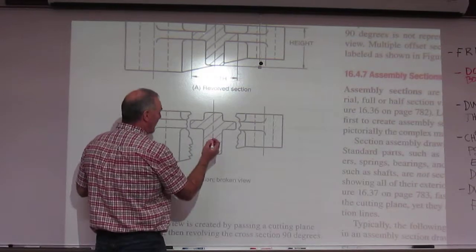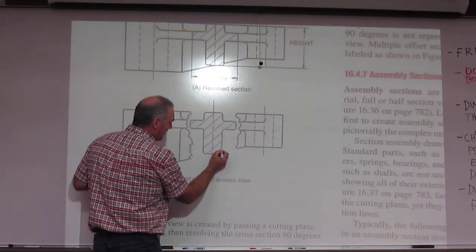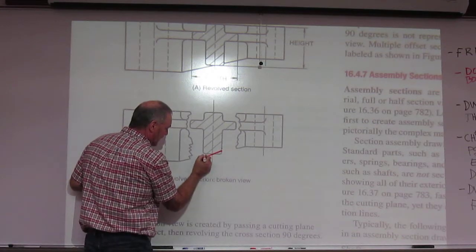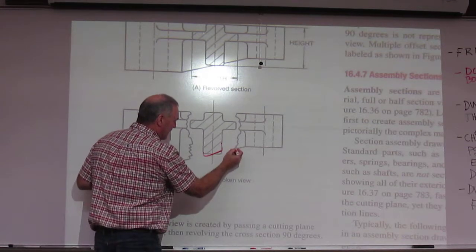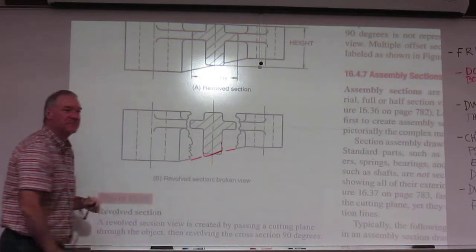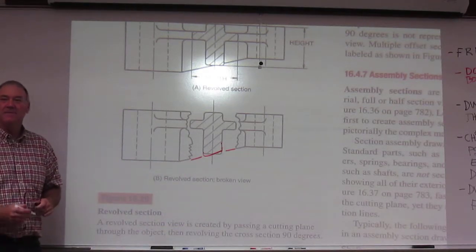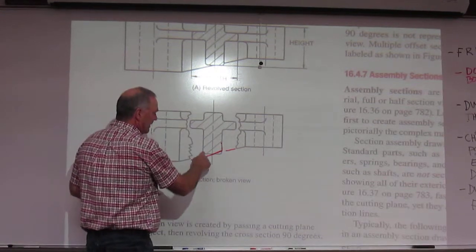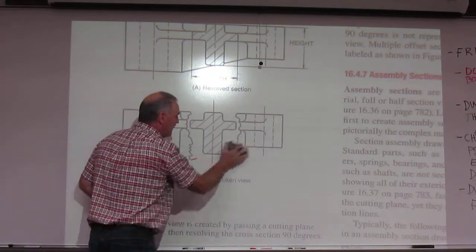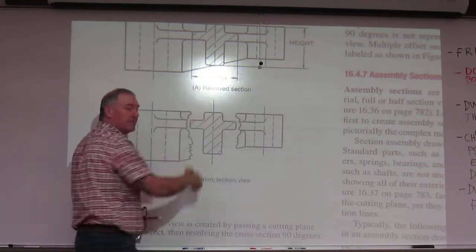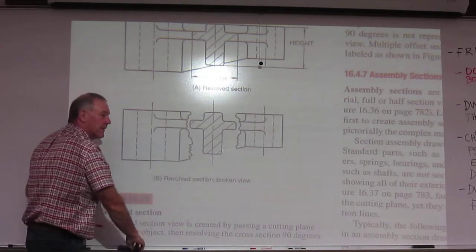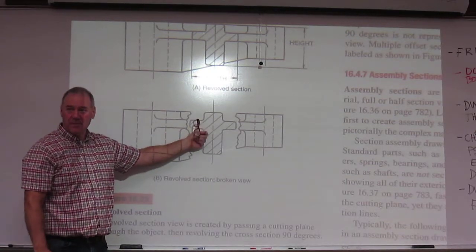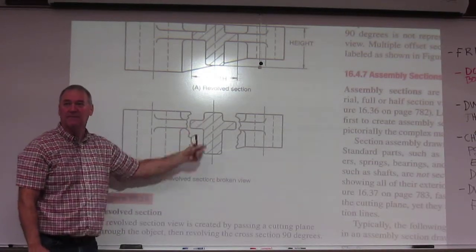I see this quite often, being as how I work with people that are learning the trade, and I'll see this bottom piece drawn like this, so it's lining up with that. It's not. Make sure you're doing it right on this center line. That's why it's square along that bottom, because it's square up in the top view. So make sure you do the full-size replica of what that handle is here.